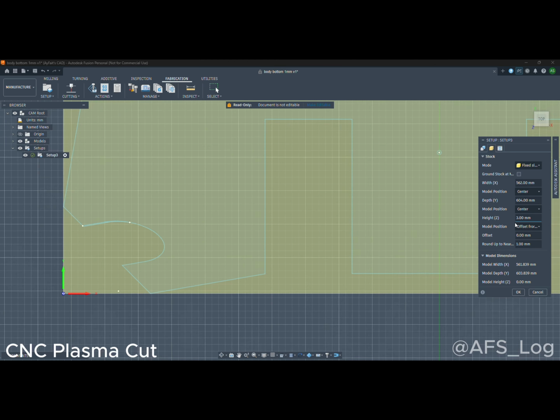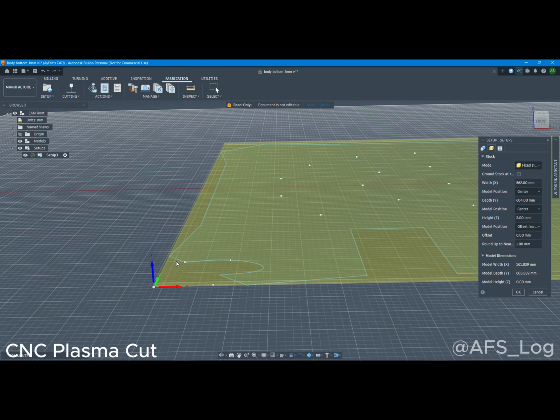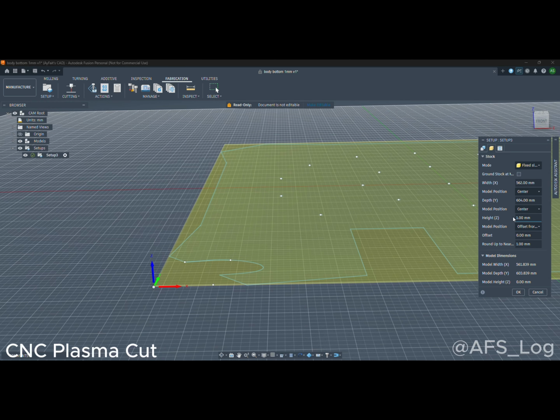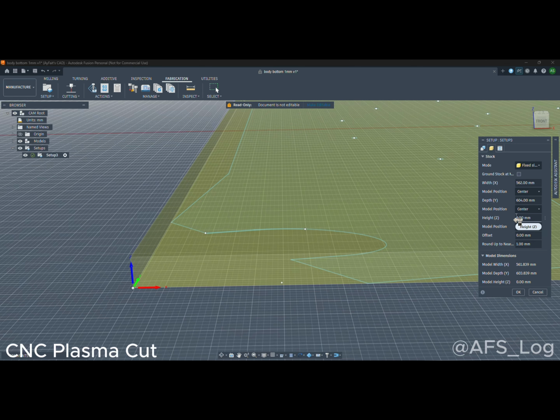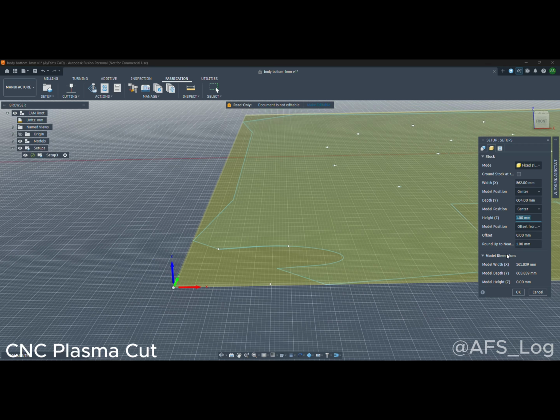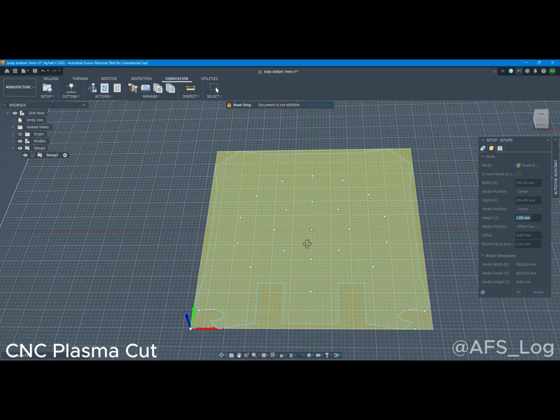It quite matters a lot because it determines the retract height, the cut pierce height of the nozzle, and it affects. So here we are cutting from 1 mm, so we put 1 mm. Now if you notice the height has reduced. If I select 9, the height has increased. You notice that? If I select 1 again, yeah. So, and you can save as default in case you don't want to always come back to that.